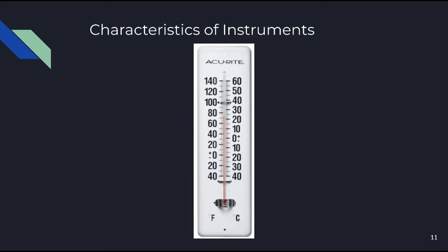Static characteristics of instruments. If we have a thermometer in a room and its reading shows a temperature of 20 C, then it does not really matter whether the true temperature of the room is 19.5 or 20.5 C. Such small variations around 20 C are too small to affect whether we feel warm enough or not. Our bodies cannot discriminate between such close levels of temperature, and therefore a thermometer with an inaccuracy of 0.5 C is perfectly adequate.